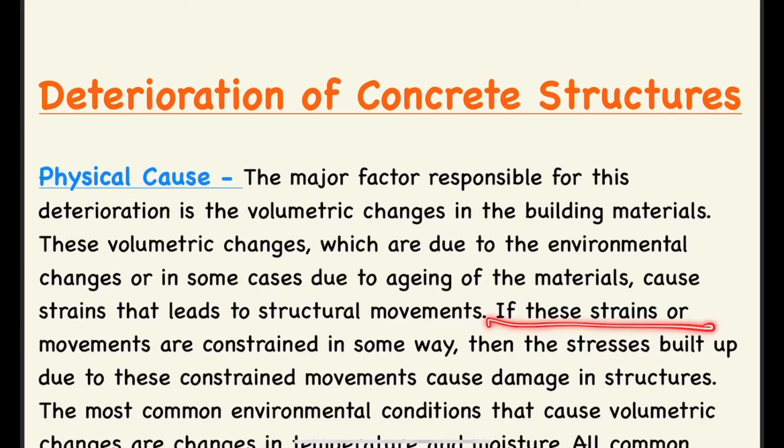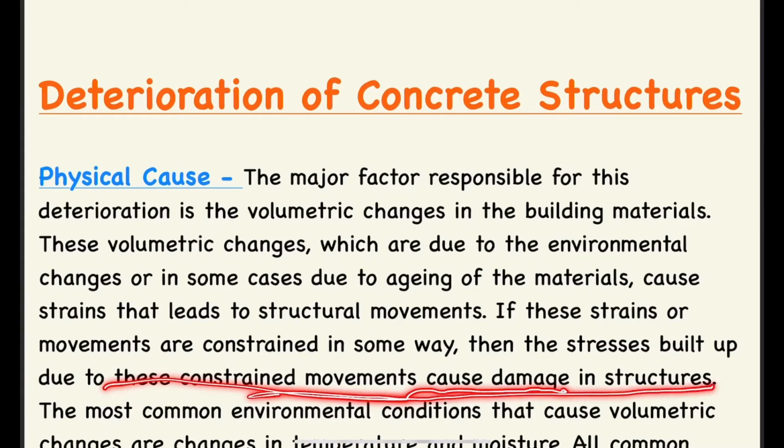If these strains or movement are constrained in some way, suppose the building materials, due to volumetric change, are not able to move or they are constrained in some way, they are packed by the particles, their particle density is very high, then it becomes difficult for the particles to move. And if they are not able to move, then stresses build up due to constrained movement, and this constrained movement causes damages in the structure.